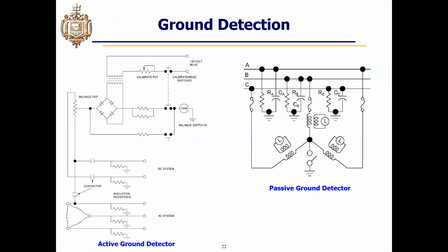And because of the concern about the effects that inadvertent grounding can have on our electrical distribution, any interruptions of power and the problems it can cause, and also shock hazards, we do a lot of ground detection monitoring. The two general types of detectors are active ground detectors, which employ an active voltage signal. You generally only see these on electric plant control panels. You're applying an active source and measuring the return current. This is a very accurate way to get the current grounds on energized buses.